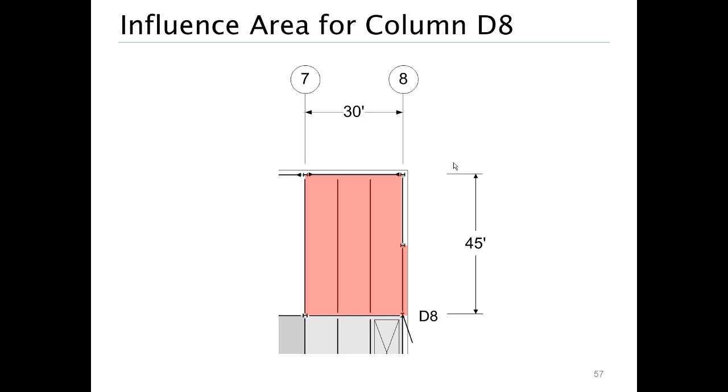ASCE 7 has factors that try to relate influence area to tributary area, but things kind of fall apart when we get to a more general influence area case. So what I'm using here is a more general definition of influence area.